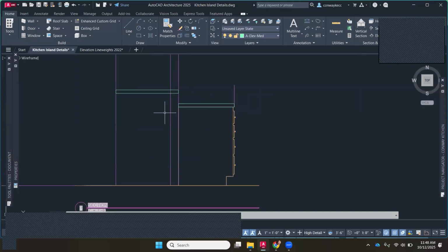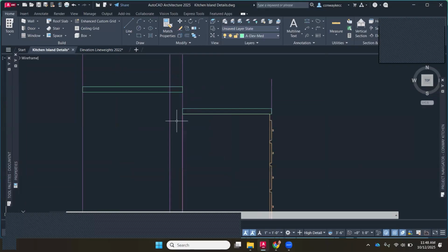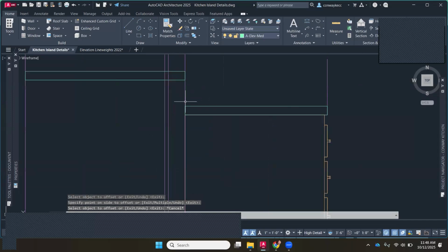Again, it's going to depend on the math that you're doing. So the way this works, and I'll explain it really quickly, is okay, drywall. We're probably going to have drywall on this side or some kind of paneling. That's usually 5/8 of an inch. So this line goes in 5/8 of an inch. Now you might have tile or something here. If you have tile, you still have to stick it on something. So you're still sticking it on drywall. So we go in this far for drywall.